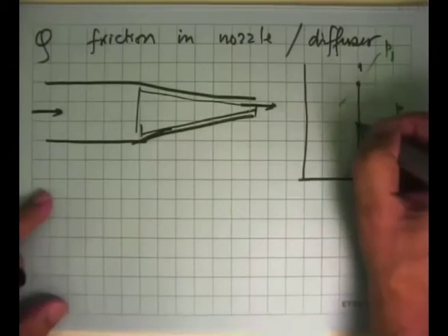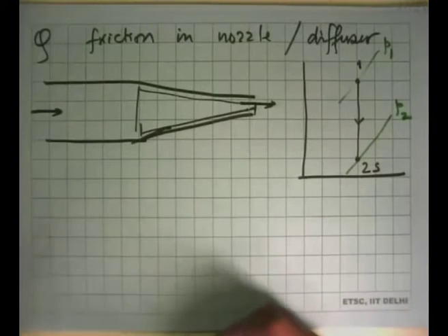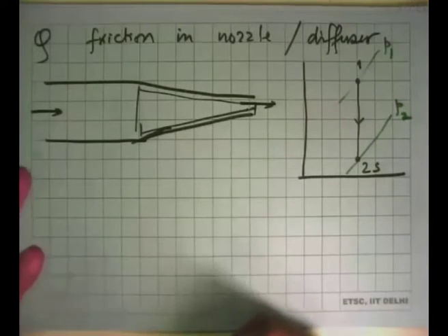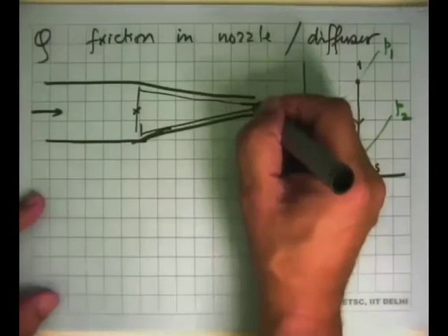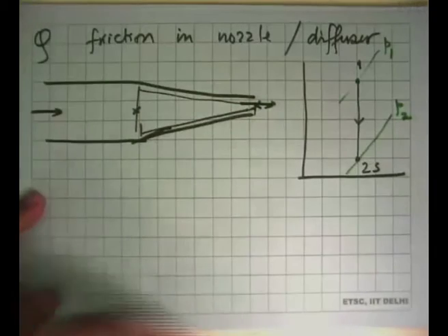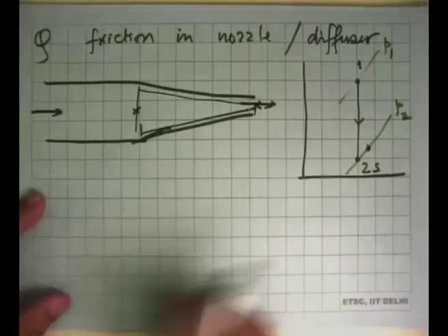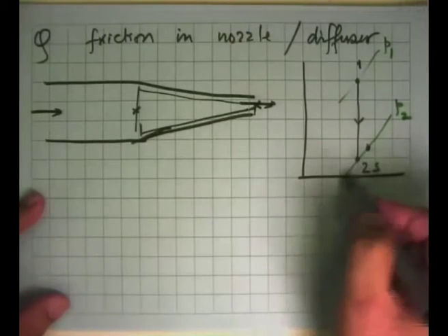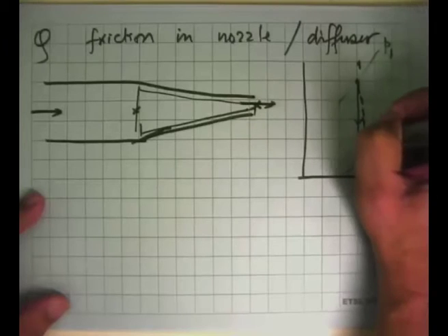So this was the isentropic nozzle. The real nozzle, because of internal irreversibilities, its entropy has to increase. But if we expand it from the same inlet pressure to the same outlet pressure with increasing entropy, that means the state has to lie somewhere there. Entropy has increased, pressure is still constant, and now the real nozzle, because of friction, does this thing.